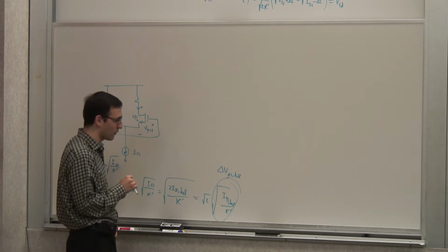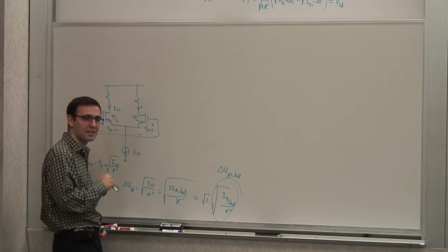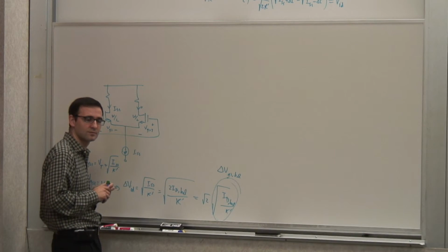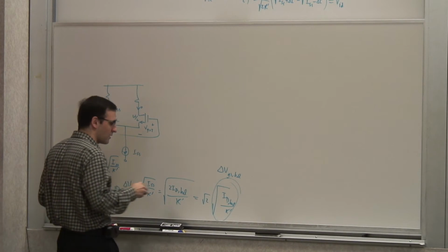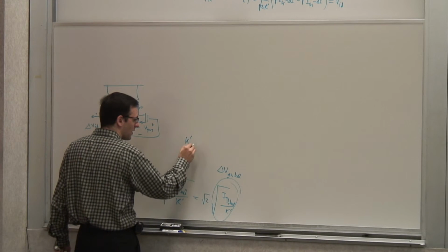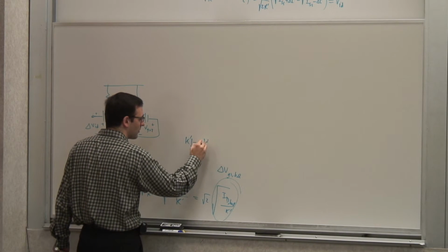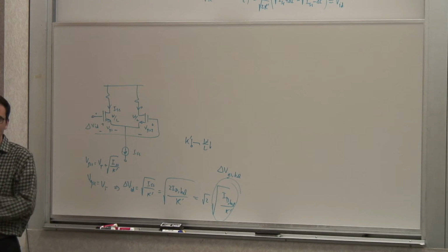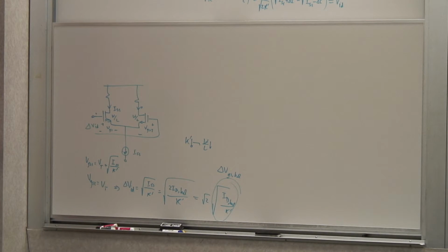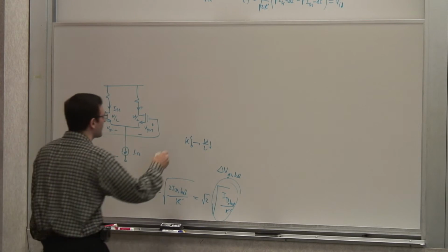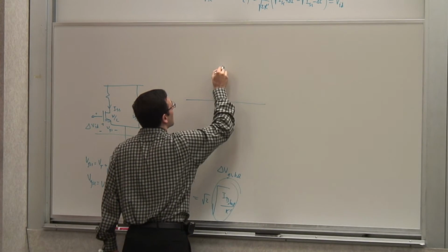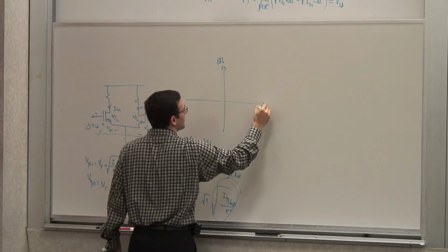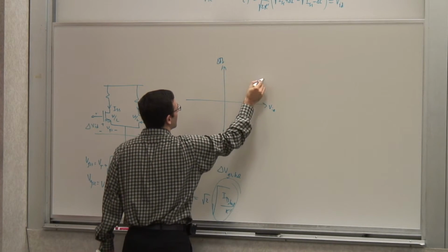Well, increase the current, that's one way, yeah. But let's say I have a fixed power budget. I can increase the current and not that power. You could lower the W over L ratio. Right, I need to lower my K prime, therefore I need to lower my W over L ratio. So I can make it smaller, use a smaller W over L. That gives me a larger dynamic range. So if I look at this transfer function, this delta I over VID,